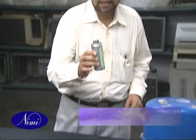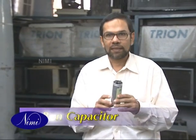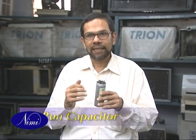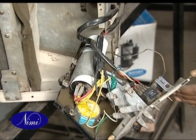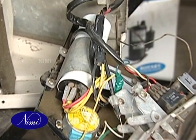Here is the run capacitor. This run capacitor is always in the circuit, and it maintains a slightly higher voltage rating so that torque is always maintained. In electrical terms, it maintains the power factor for the compressor, so it has uniform torque available.